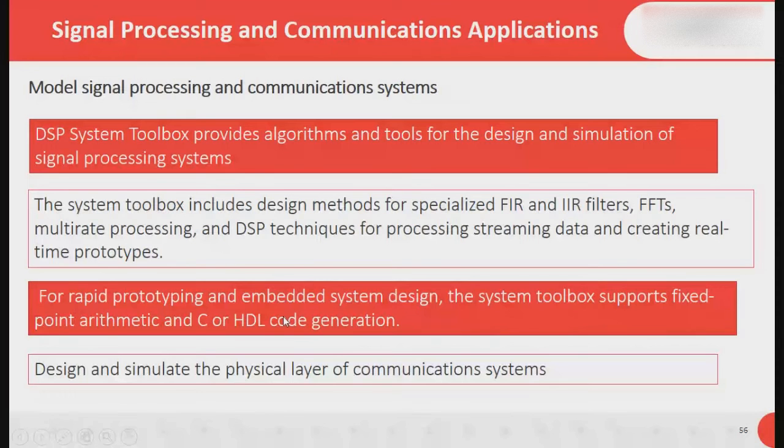Okay. So the communication system is used to design the physical layer part of it. In communication we also have the WLAN Toolbox, the wireless local area network toolbox. And using the WLAN Toolbox, you can interface SDR hardware. If I'm talking about low-cost SDR hardware, there is the RTL-SDR, which costs only 1 or 2,000, a TV tuner. If there is only a receiving antenna, just connect it with MATLAB, and whatever free signals are available in the environment, if you know the frequency, you can log that data in your MATLAB, like FM data or flight tracking kind of things, using the Communications Toolbox.